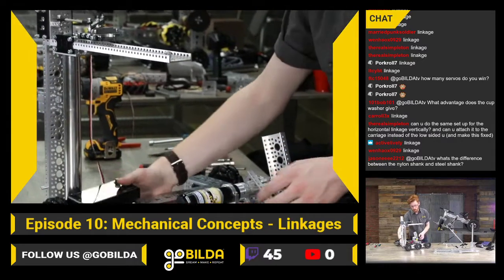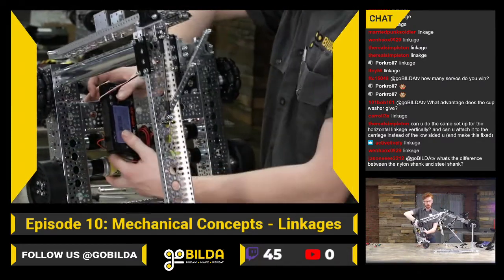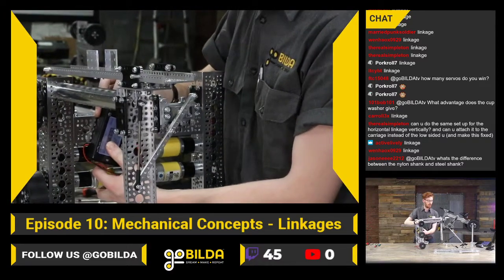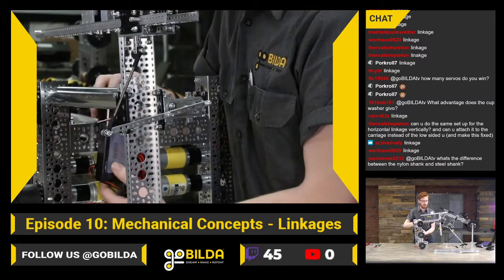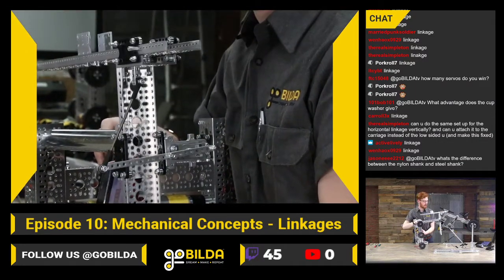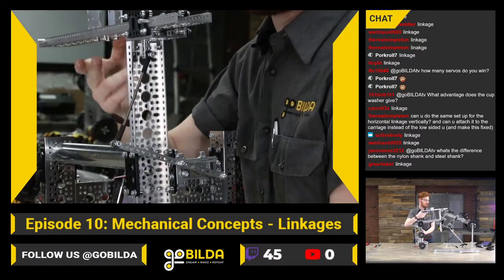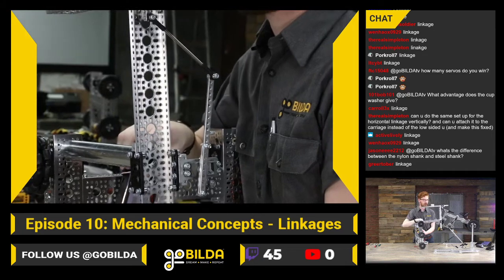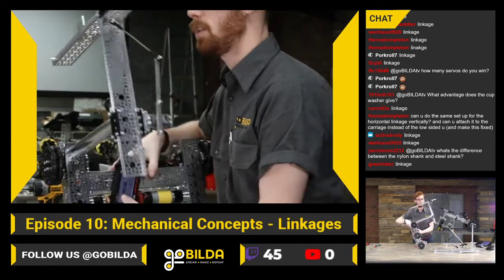Easy way to show you would just be to tilt this guy all on its side. You can see it'll have kind of a problem picking up that load because it's really designed around a lot of speed compared to having a lot of torque. And you can see it has no problem moving it near the ends, but as you get to the center of that throw, it is not going to like doing a whole lot.